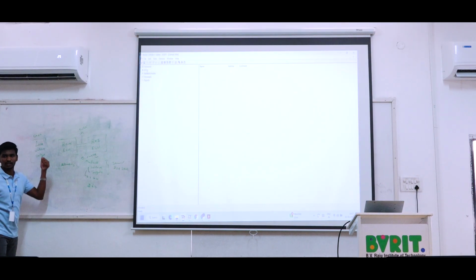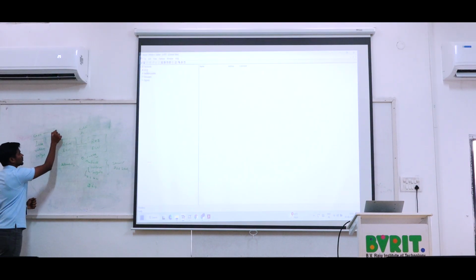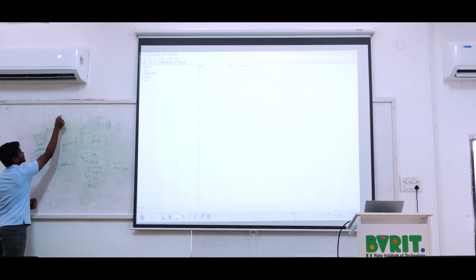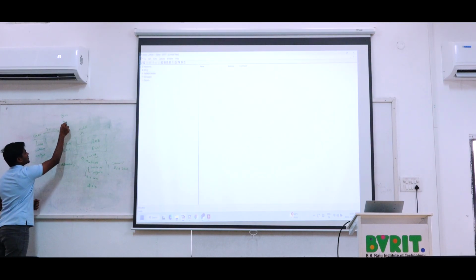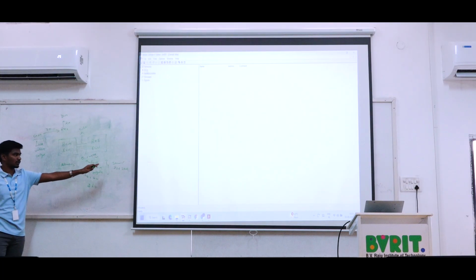We can give any number as per the OEM's requirement; just now, for the example, I give the ID number 400. This ID 400 will collect the values of lock, unlock, and tailgate. We set it as TX from the RKE ECU, and it will be received by the BCM. This is what we are going to do in this tool.